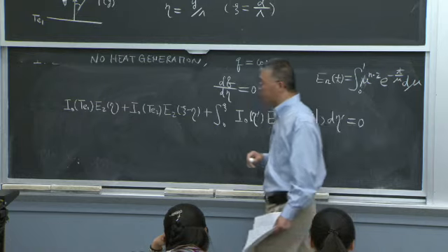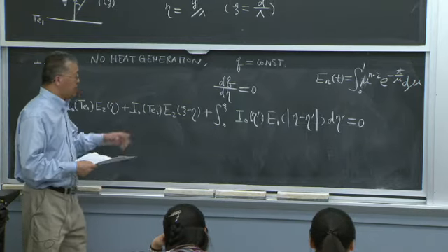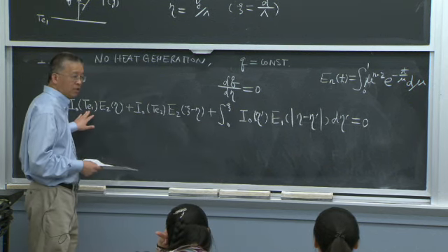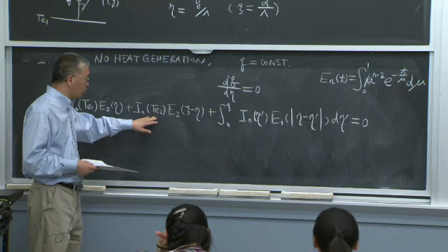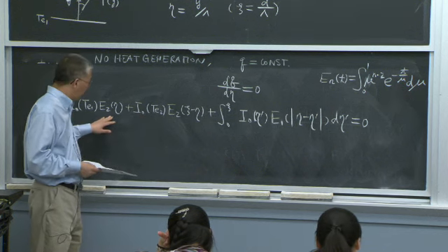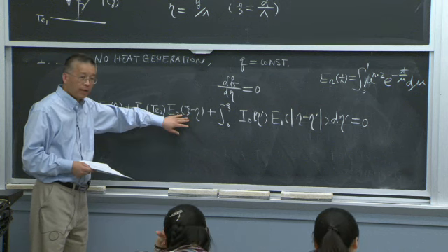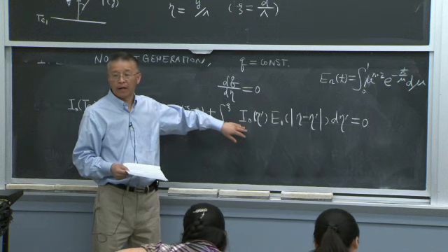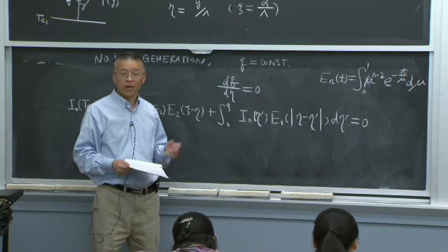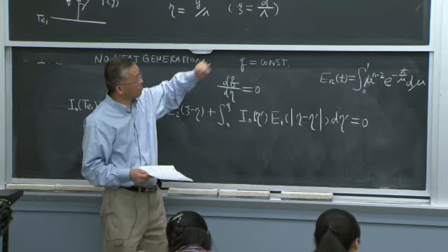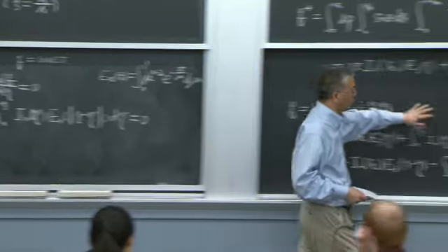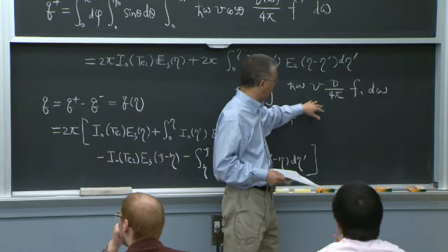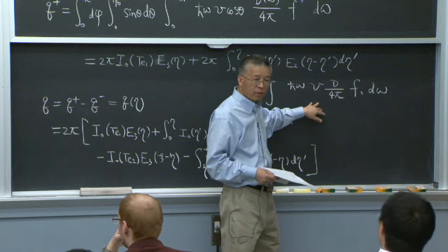Okay? So now this is the equation you need to solve, given the boundary condition: on one side is TE1, on the other side TE2, and the mean free path and film thickness determine cosine, right? And then you need to solve this equation to find what is I0 at each point. I0, remember, is related to my temperature, right? I0 is related to F0 because this is the photon property, density of states, frequency omega, which you know from the solid that you're dealing with.